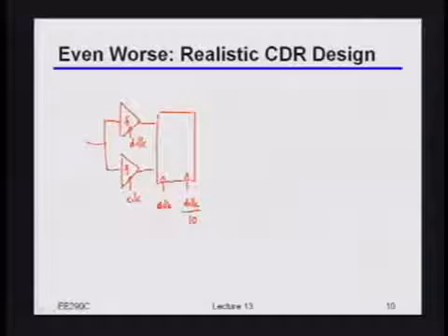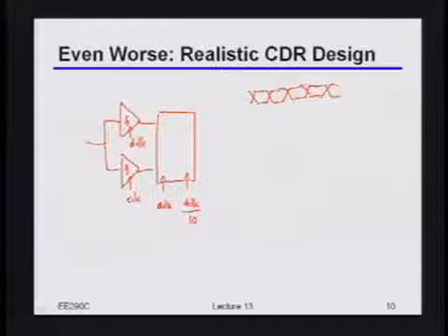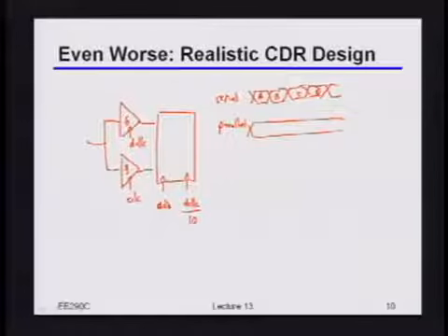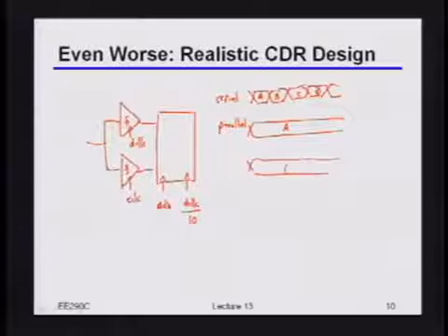So the idea would be that I have my incoming data stream that's coming in at, again, let's say 12 gigahertz or 12 gigabits per second. So this is my so-called serial stream. And the parallel stream would basically be, if this is, let's say, A, B, C, D, the parallel stream would be something like, I have this A for some period of time. I also have that B for some period of time.